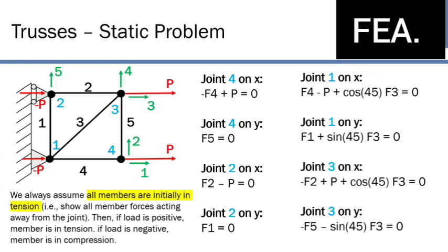Obviously, in a truss system, we have two-force members, and because we assume that the forces point out of the member, that means we're assuming them to be in tension. That means if it's a negative value, it's actually going to be under compression. So we can assume everything's under tension until it's negative, then we know it's compressive. That makes sense, everybody? Does anyone not know how to get to this point given a truss system?